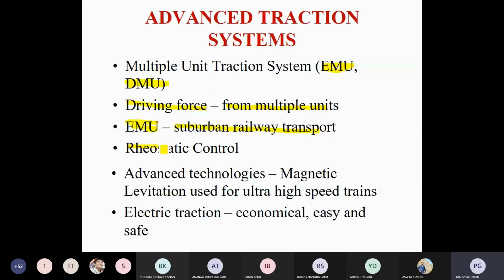Okay, but the main problem is that you are using rheostatic braking or dynamic braking, so no regenerative braking. Only plugging is sometimes used for backward movement of the train. But in most cases you use rheostatic braking. Basically, regenerative braking is only possible for long line travel. Otherwise, regeneration requires some time.